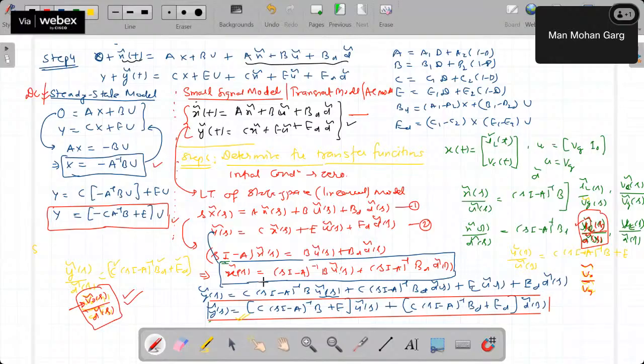So this is the detailed explanation which I have told you. Now you can directly obtain the state space equation in mode 1, mode 2. You will get A1, A2, B1, B2, C1, C2. You know the duty cycle value. With the help of that, you can get A, B, C, right? Now, once you get A, B, C, then we can get this value X equals minus A inverse BU. You can get the Y value also. So the X, Y also we got.